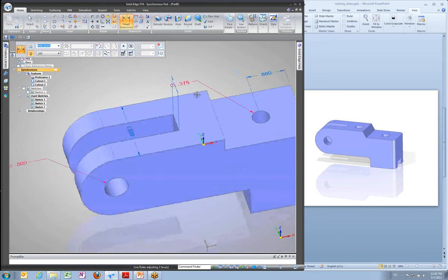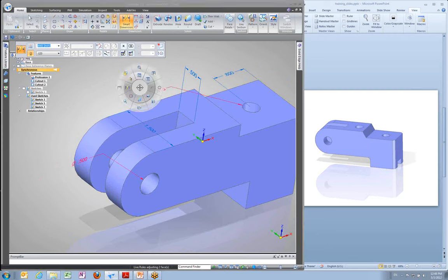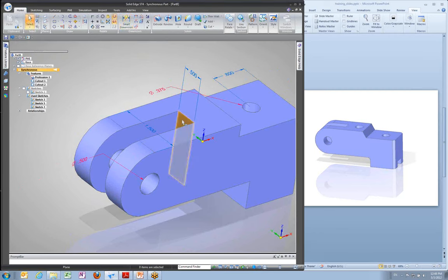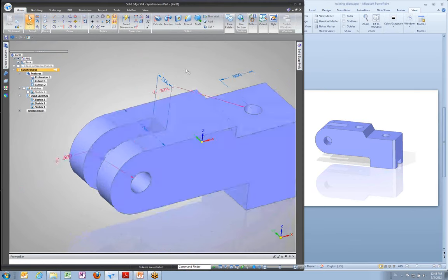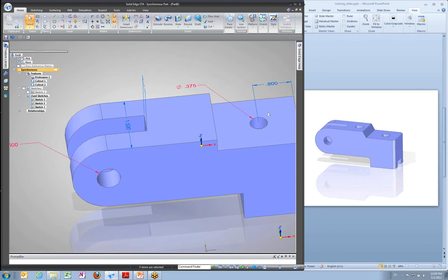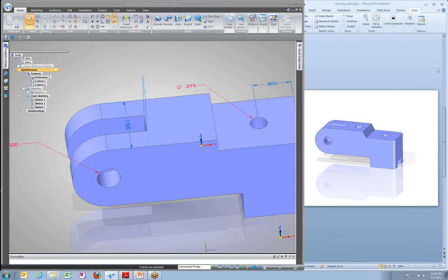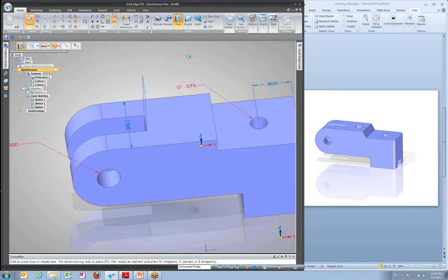Okay, last thing I need to do is drop another hole on this face here, which is a countersunk hole. Now I'm not sure if I've got enough space for that, so I'm just going to switch back to my select tool, grab this face, and just pull it back a bit, just until I've created that hole and I know that I've got enough placement for it. So last time we did this by drawing a circle and using it as a cutout. This time we're going to use the actual hole command.